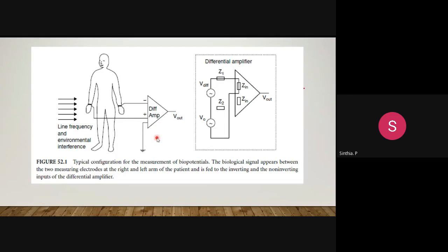Here the preamplifier used is a differential amplifier. The design of this amplifier is very important, because this is your first stage of the signal conditioning process. This is the stage where the quality of the biosignal picked up is set. If properly designed, the preamplifier can eliminate, or at least minimize, most of the signals interfering with the measurement of the biopotential. It will not totally reject the noise, but at least you can maintain the level of noise interference at a bare minimum.